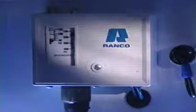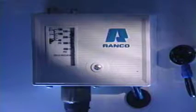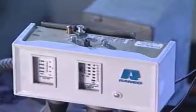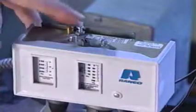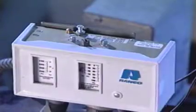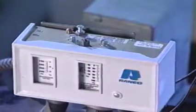One type of switch that's commonly found on air conditioning and refrigeration systems is the pressure switch, which opens and closes its contacts based on the pressure it senses. The high pressure switch is connected to the discharge side of a refrigeration system and opens its contacts if the pressure reaches a higher level than the predetermined set point. Most high-pressure switches need to be manually reset once they open their contacts. This helps ensure that the system will not operate under unsafe conditions.